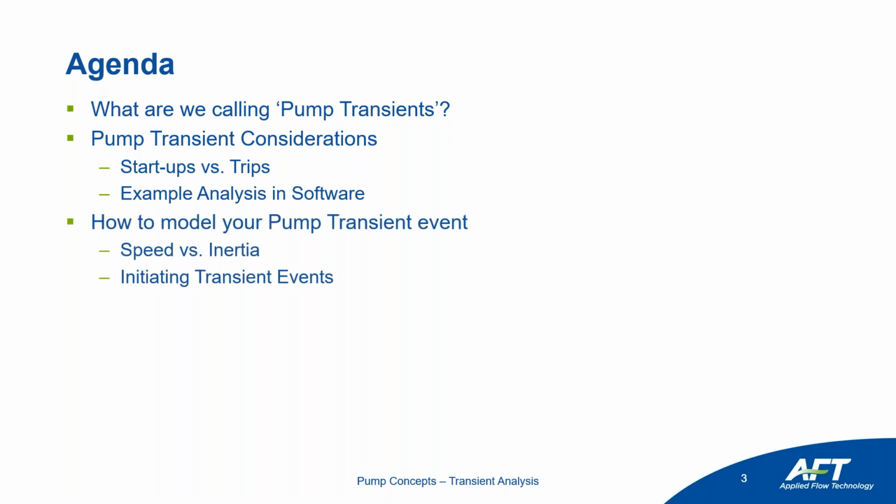So we'll take a look at those different considerations we want to take. What sort of things are we looking out for as we're doing the analysis? As we're also doing the analysis, we'll talk about how to model your pump transient event. Again, the big difference is between speed modeling and inertial modeling. That'll make more sense in the context of the software, and we have some good examples comparing the two. And then we'll also take a look at how we can initiate these transient events.